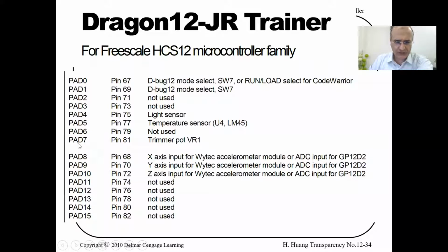Let's read the potentiometer, convert it to a voltage number from 0 to 5, and display the voltage on our 7-segment display. Just like we're doing a voltmeter, and we can get a voltage from anywhere, from a battery, from another external potentiometer, from any source, from a sensor. Okay, display it on the 7-segment display as a number from 0 to 5. Later on, when we take serial communication, we can send it serially maybe to the computer or to MATLAB.